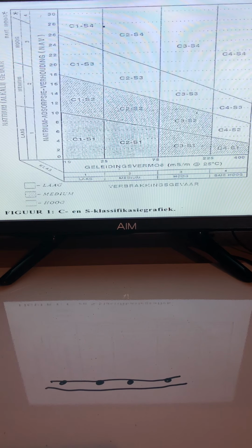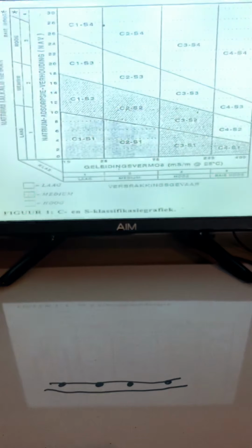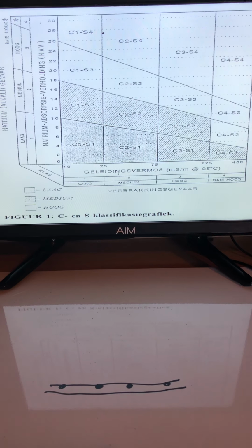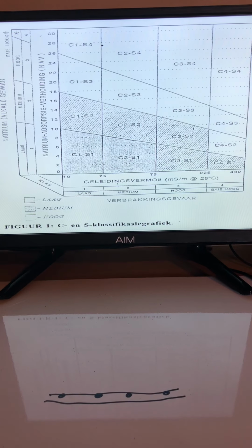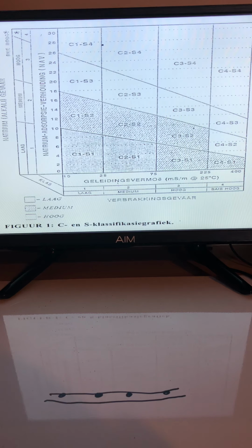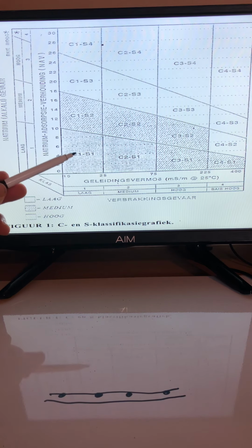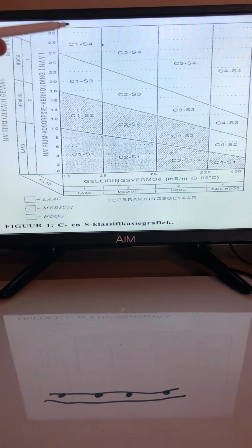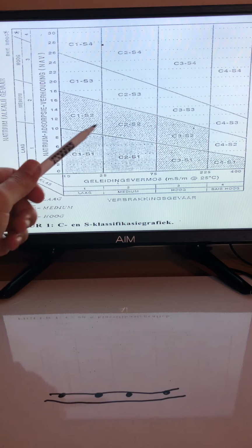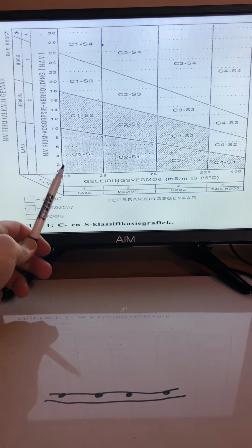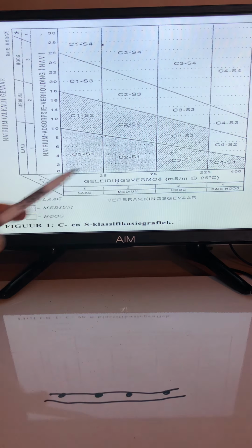So that's why it also plays a very big role in knowing what irrigation system you have and how to use your irrigation system. So this graph is used especially in the US, and sorry about that. What it does is it is a way for us to classify the salt content and the quality of the water. So right here you can see C1, S1, and then C1, S2, S3, S4. So the S's get higher up this y-axis, and you can see C1, C2, C3. So the C value gets higher up the x-axis.